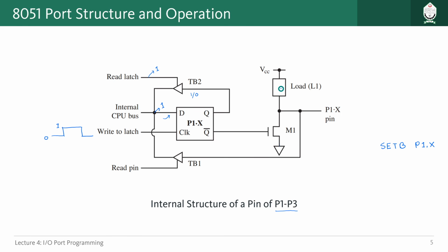This can be considered just a simple resistor, like a pull-up resistor, which connects with the 5 volt so that if needed we can get the 5 volt for digital circuits. So this acts as an internal pull-up resistor. We will properly understand what purpose it has in our circuit.